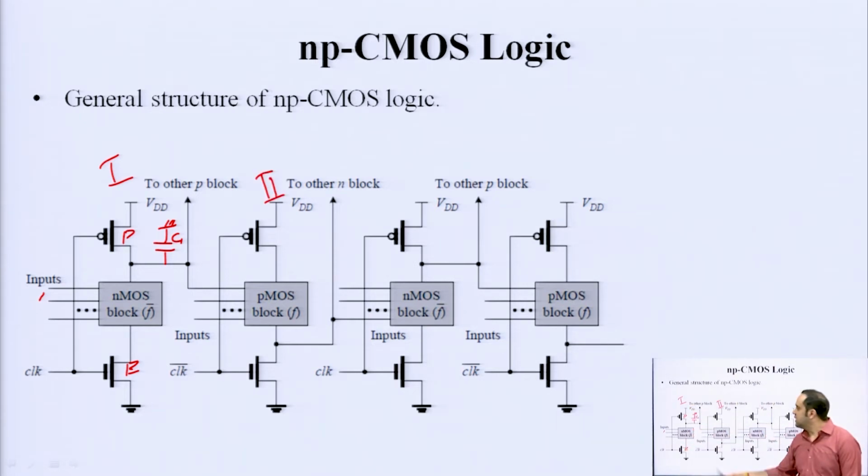For the output of stage 1, there is no inverter in the middle, no other circuitry. It is directly connected to one of the inputs of the pull up network, which consists of PMOS transistors. Here, if it is visible, F bar is written, which means it is implementing inverting logic. There is an F here which means it is implementing non inverting logic.